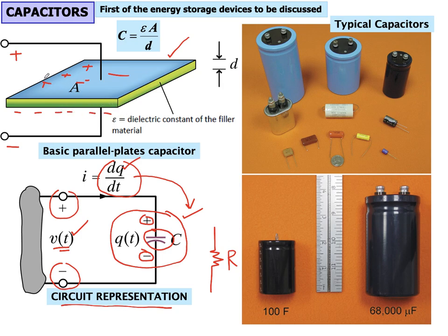These positive charges have electric field going out of them, and for the negative charges, the electric field is going inward. Because you have a concentration of positive charges on the top plate and negative charges on the bottom plate, an electric field will be produced going from the positive plate to the negative plate. So the energy stored by the capacitor is stored in this electric field.